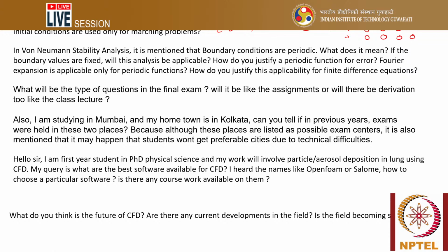Then you can see that everywhere the same fluid flow is taking place. Whatever is going out from this first domain is the inlet of the second domain. So whatever flow is going out is coming in for the same domain. You can see it is repeated, so it is periodic in the axial direction. This is known as periodic boundary conditions.